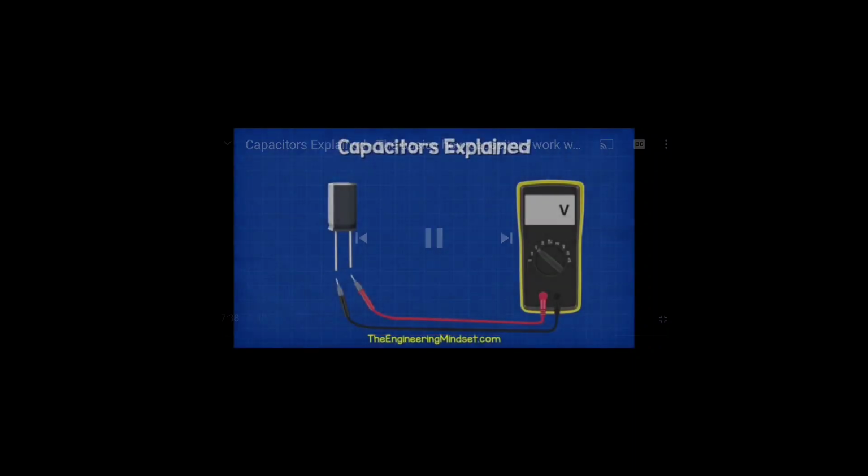To check the voltage, we switch to DC voltage on our meter, and then we connect the red wire to the positive side of the capacitor and the black wire to the negative side. If we get a reading of several volts or more, then we should discharge that by safely connecting the terminals to a resistor and continue to read the voltage. We want to make sure that it's reduced down into the millivolts range before handling it, else we might get a shock.